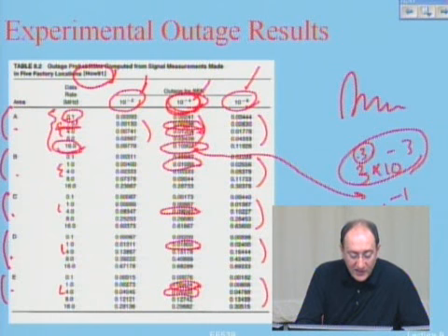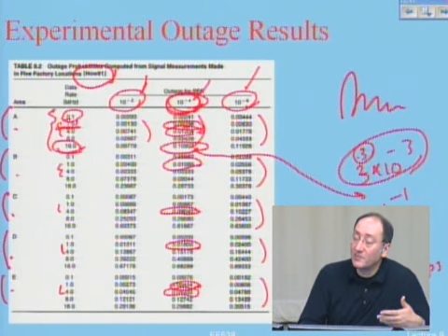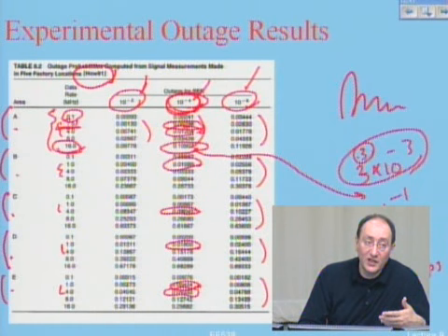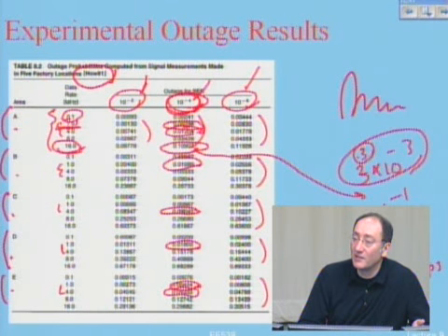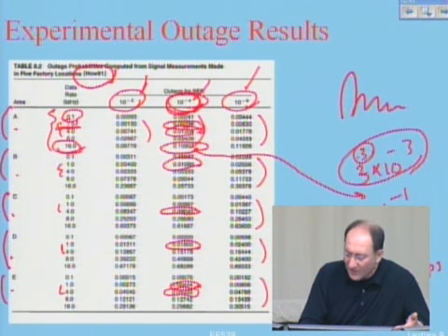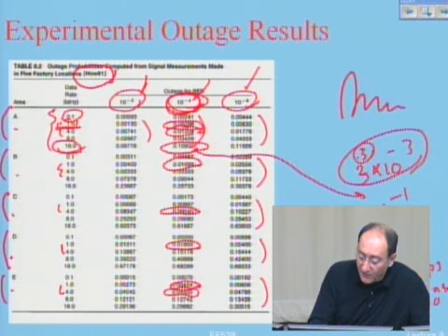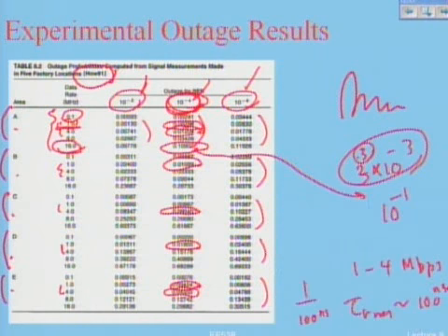If I go with that 1%, I see there is a relationship. Data rates around 1 to 4 megabit per second are the data rates which are acceptable for what? For indoor channels. What was the tau RMS for indoor channels? Do you remember? Tau RMS from the same measurements was roughly around 100 nanosecond. What is the inverse of 100 nanosecond? 1 over 100 nanosecond is 10 megabit per second. So if my data rate is like 10% of that, I have good data communication.